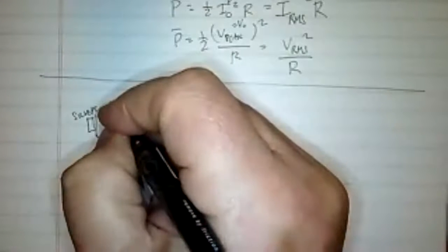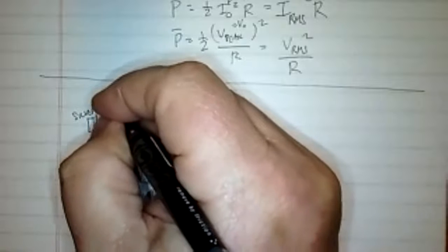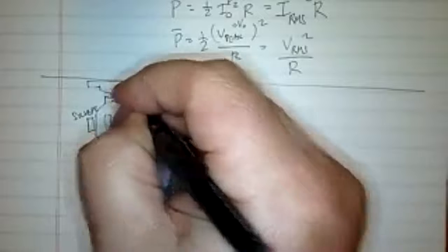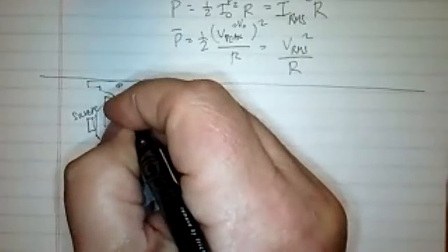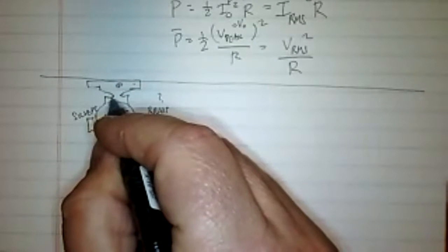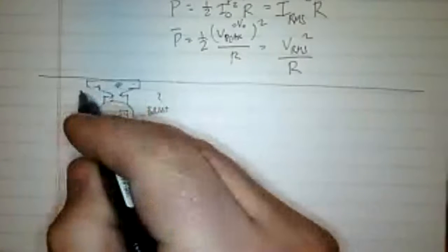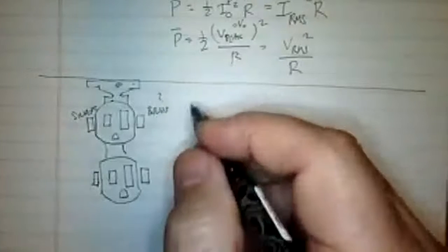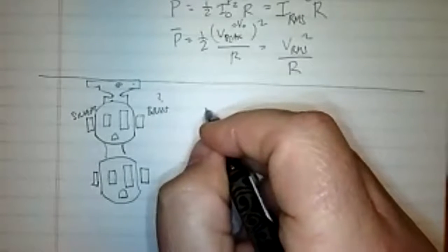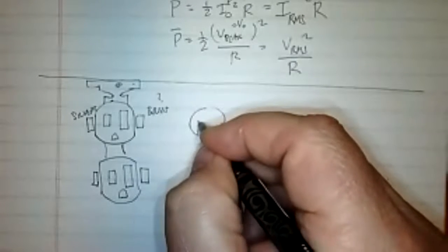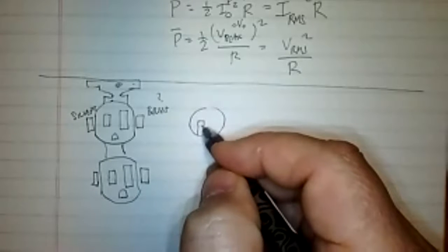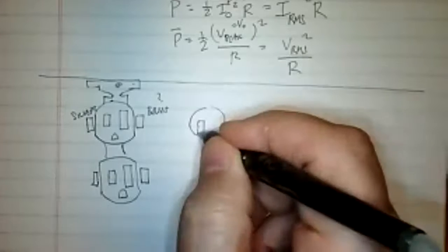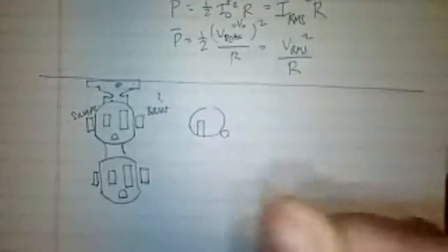If you look at it, there's a little piece that comes down here and goes out here, and it has these little brackets, and a place where you can put a screw. That thing can actually allow you to strip your wire. It's not a very good stripper, but it can do it. If you turn around the back, there's a little gauge that tells you how long you should strip it. And it's also got a hole in there, so once you strip it, you can just jab it in there, and that does the same thing as connecting it to a screw.